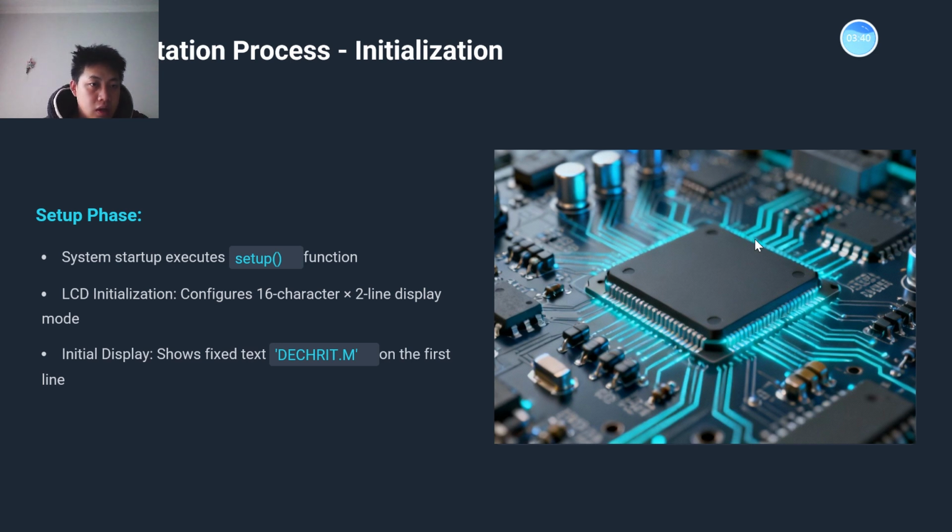Okay, then the implementation process, initialization, the setup phase. At system startup, it executes the setup function and LCD initialization, which configures the 16 characters by 2 lines display mode, and the initial display shows fixed text, a director name, on the first line.